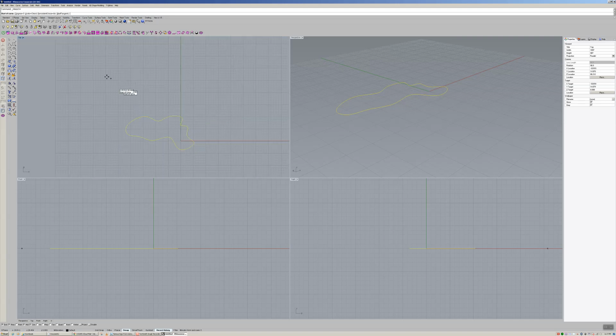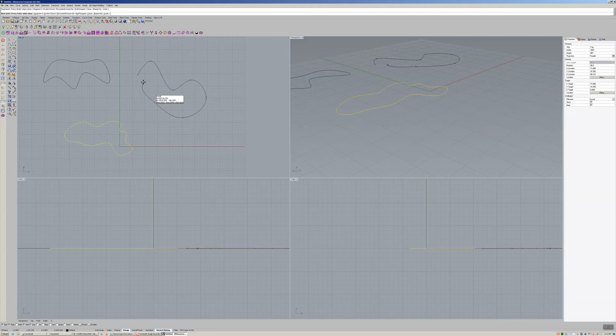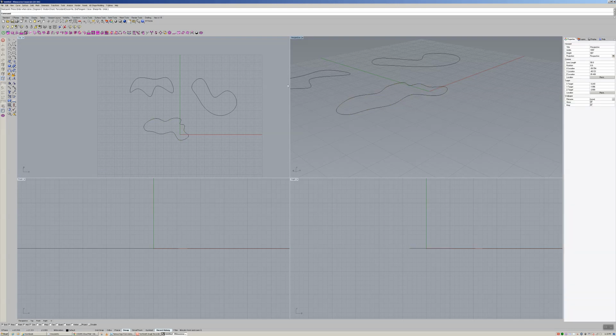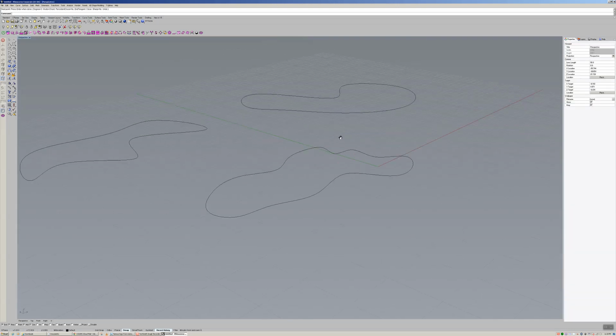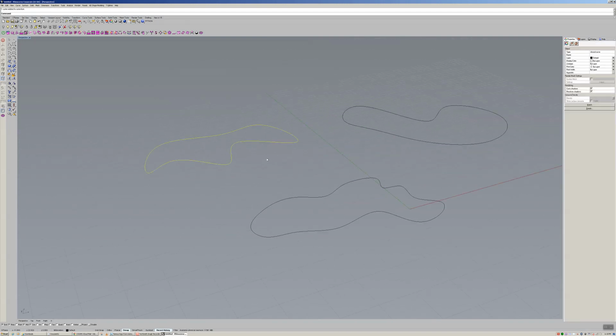Okay, so I'm here. I'm going to make a few more curves, and I'm just making whatever. Click, click, click, click, click. Now you see it's talking to me here. So when I get close to that point, you see I'm moving close. Watch what it says. It says point, or it'll say end. And that means that I've connected it now. When I left click, it's now done. It's a connected curve. Now this is what makes 3D special compared to using Illustrator or any kind of two-dimensional drawing package.